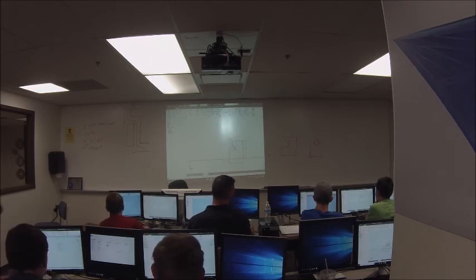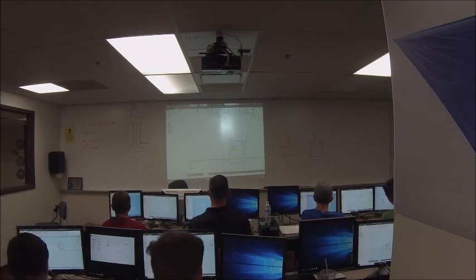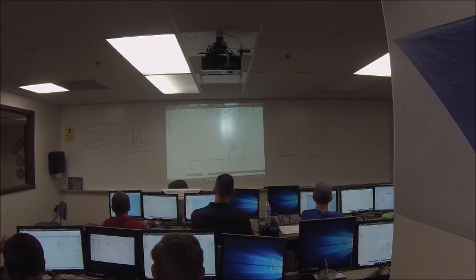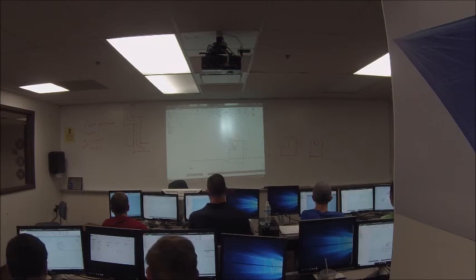Oh, you did what he did. Okay, so escape out. You actually deleted your point in the middle. You wanna get it back? So go over to origin, click the center point, and click project geometry. Yep. Now you can do what you were trying to do earlier.